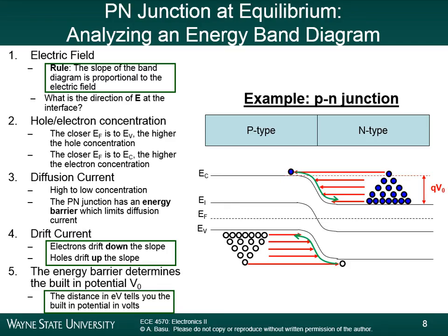electrons and holes, right? That's correct. It will change. Well, even if you put two dissimilar materials together, you still can't generate current out of it. The drift and diffusion currents will always balance at equilibrium, even if you have two dissimilar materials. But the band diagram will look slightly different.